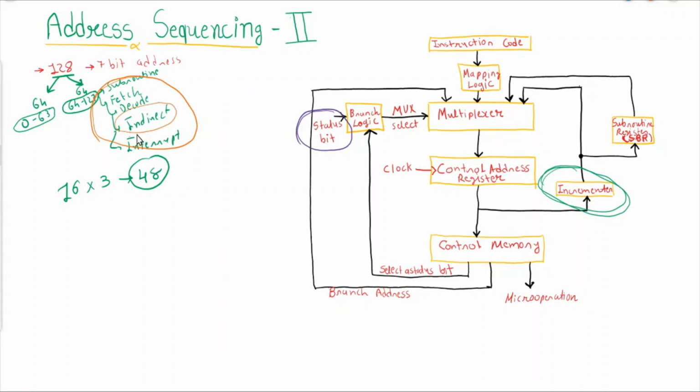If we do not have a subroutine, then there will be a separate instruction for direct addressing and another separate instruction for indirect addressing mode. So there will be one AND instruction using direct and the same AND instruction using indirect, which will result in duplication of code. So this routine helps us to save the control memory space, so more number of instructions can be accommodated.